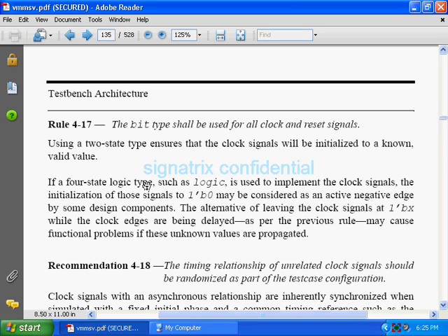The event will trigger when the passage of clock comes. Here the event triggers at 0 simulation time because there is a change of signal from x to 0, so your block is able to see the transition. But in SystemVerilog, because we have 2 states, by default it is 0, and 0 to 0 is not a transition. 0 to 1 is a transition. In this way we can avoid some of the race conditions.